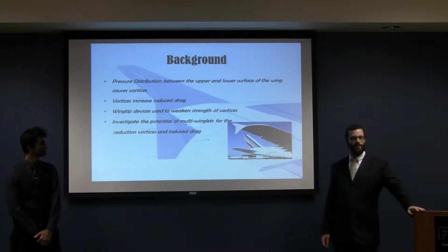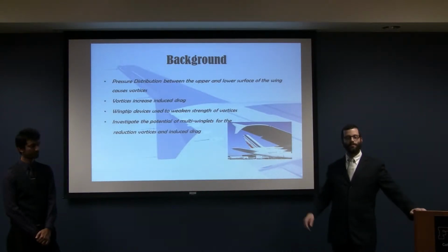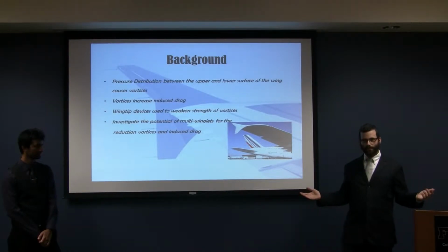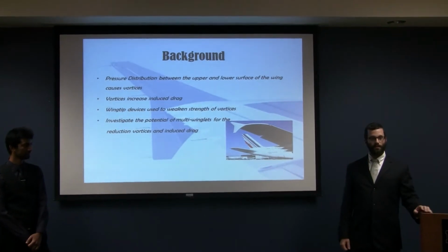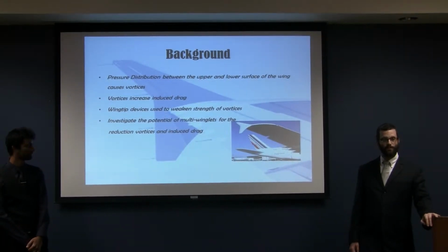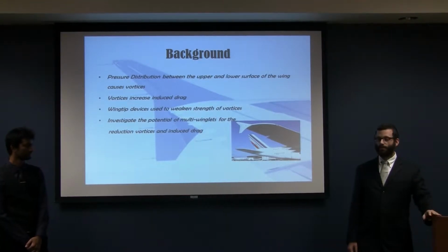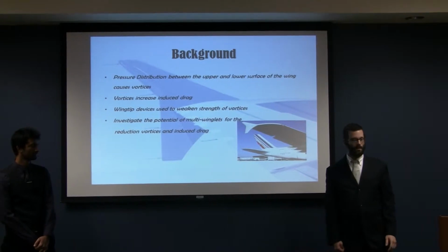Lift forces are created by the greater pressure forces on the lower surface of the wing and the lower pressure on the upper surface of the wing. These forces tend to equalize at the wing tips, creating vortices. These vortices create additional induced drag on the aircraft. The more induced drag on the aircraft, the more fuel consumption. Therefore, it's important to address this issue. One way of addressing this issue would be with winglets.